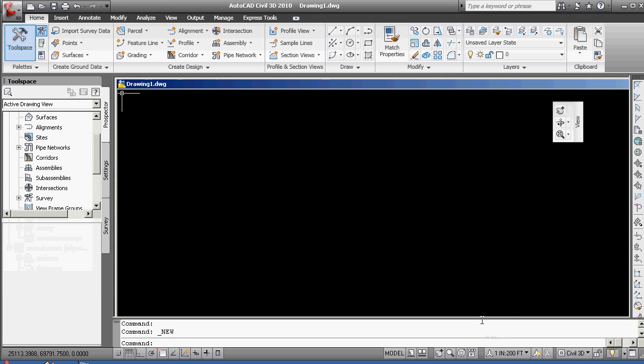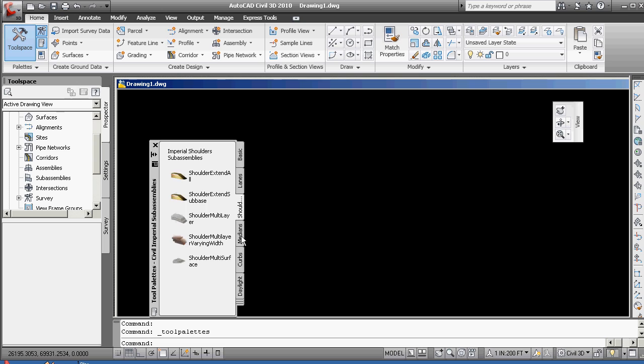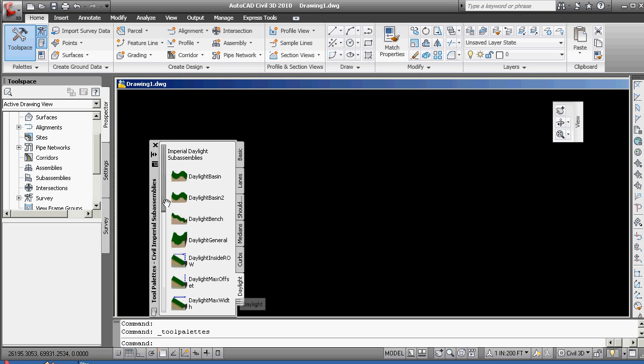The other visual check that will very often be problematic will be if you go here and click on that, which is the tool space, if you do not get this here. Now I'll cover if you do not get that visual, which is showing you the more or less straightforward set of assemblies. If you do not get that visual check, then there's something a little bit more awry in your C documents and settings, application data, AutoCAD, and so on, down to the point where you have to kind of switch out your support directory and switch something back in there.